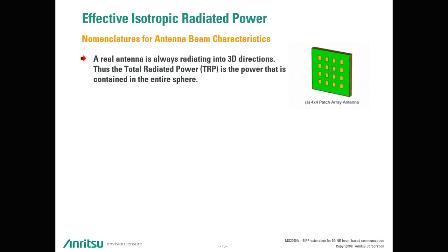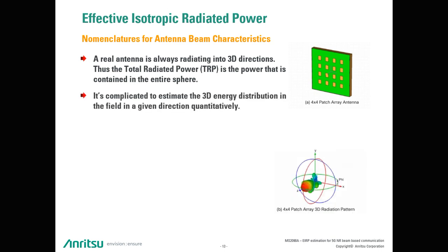For the understanding of the given topic, it must be clear that the radiated power of the measured antenna will always be a simplified view on a very complex topic. In general, an antenna is always radiating into a three-dimensional sphere. It would be correct to take power measurements at infinitesimal points around this sphere in order to get the figure for the so-called total radiated power of the antenna.